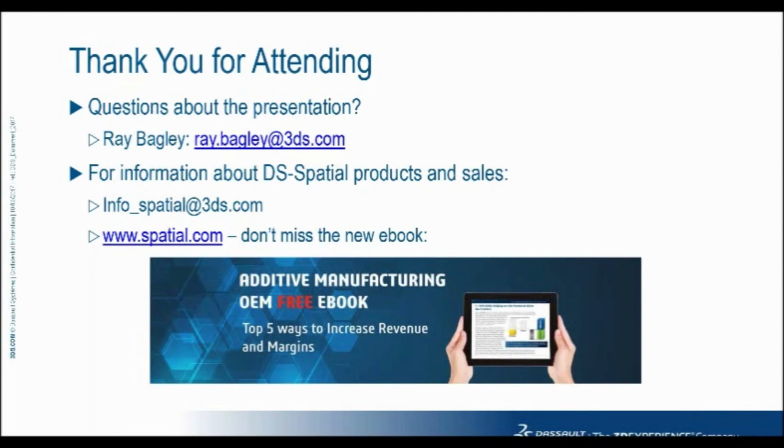Now that's not, I don't think, something we're ready to say is fully automated. You're still going to require some user input to drive that process to specify where you want to break up the process between add and subtract and add and subtract. But the automated toolpath generation for each step is there and available. And of course, you couple that with a driver specific to the machine so that you get good G-code for that machine and not something generic. Then we're ready to enable those machines today.